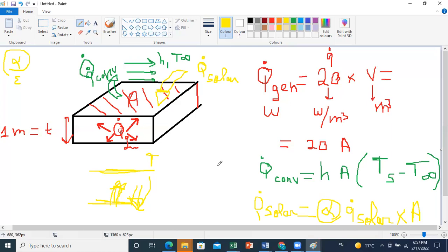Yes. Okay, now because you have the top surface, which is characterized by a certain temperature Ts, and the environment is characterized by a different temperature, you will have a radiative flux. So you also have Q dot that is emitted by your surface, a radiative flux from your rectangular box towards the external environment. How can you determine this flux? Multiplying the emissivity times the flux of the box times the area. Epsilon times which flux of the box? Did they give us the flux of the box? No, I mean the Q generated.